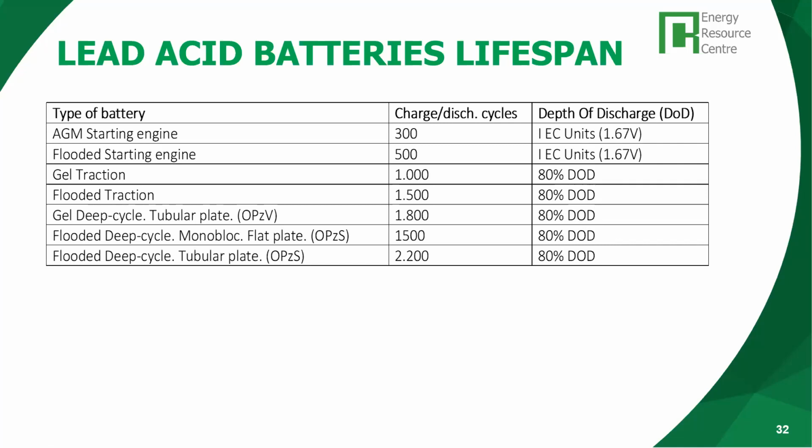I stick to what engineer Antolin from Inventus told us. He works for a battery manufacturer, and he recommended 50%, if you remember. So 50, 60, eventually a deep discharge for a particular application, an emergency, once in a while, is not so problematic, but systematically discharging lead acid batteries that low is not advisable.